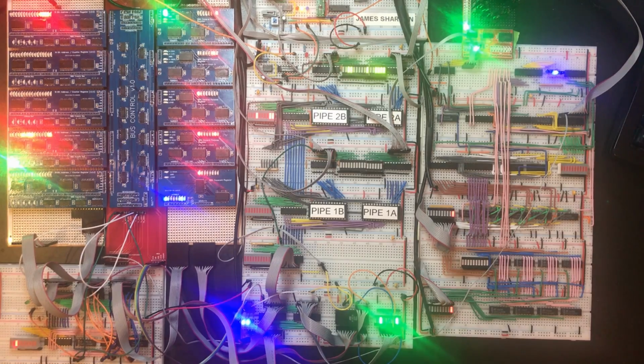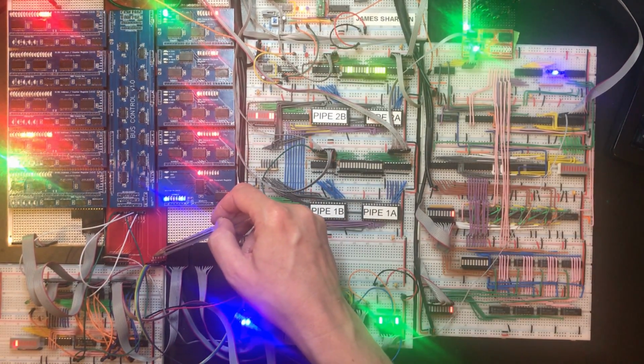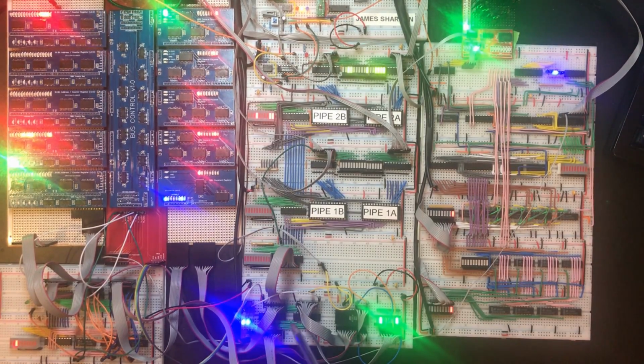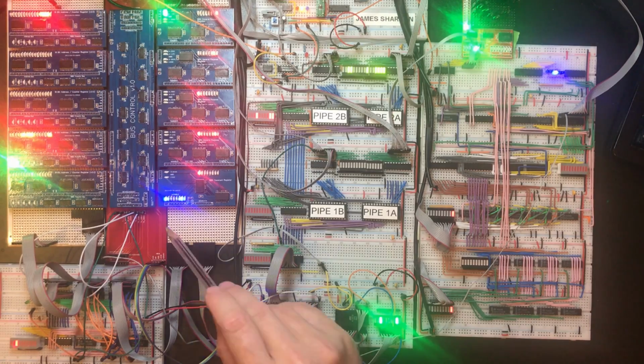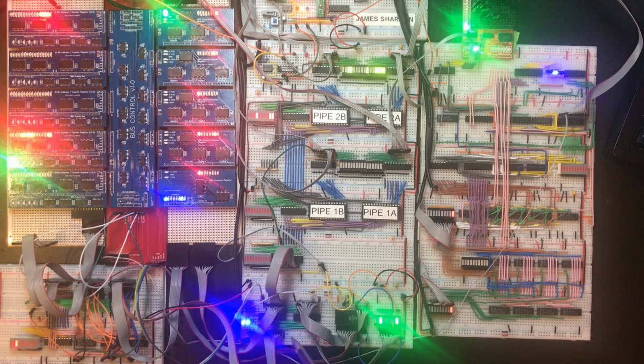And that's a problem in and of itself because that will drop the direction line. This circuit in the memory bridge will reverse itself and it will start pulling what's on the main bus and pushing it onto the memory data bus that the memory chip is going to be also contending with, which would be bad. So we need to do something about that.